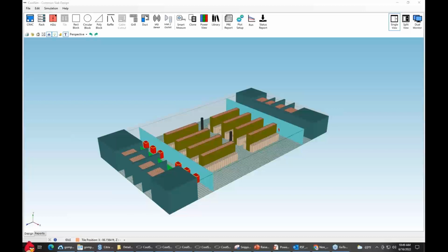Okay, so here are some questions coming in. What is the horizontal line that separates north and south plan? What is the impact of underfloor obstructions? Sure, underfloor obstructions are always an issue, Mitch. Yeah, there's a target percentage of obstruction. Generally speaking, on the underfloor, if the obstruction is not greater than 30% of the cross-sectional area in height, then it tends to not be as much of a problem. So you don't want it to be more than 30%, generally speaking, of height.